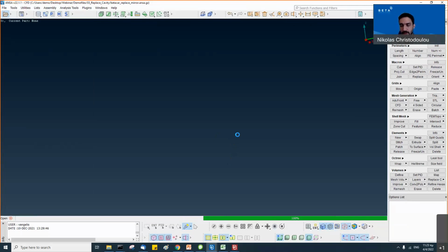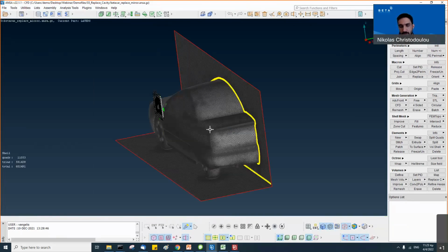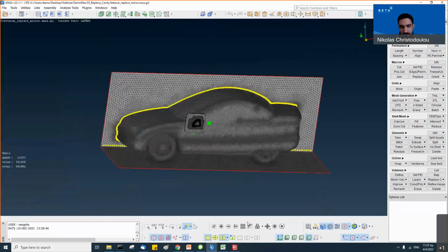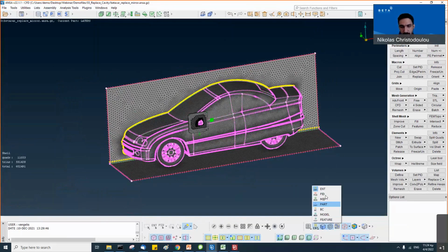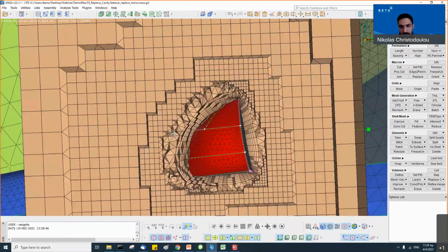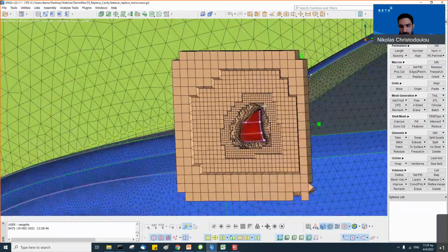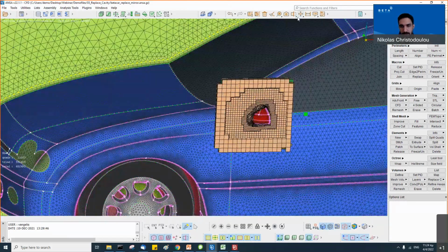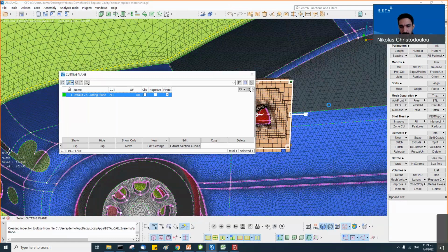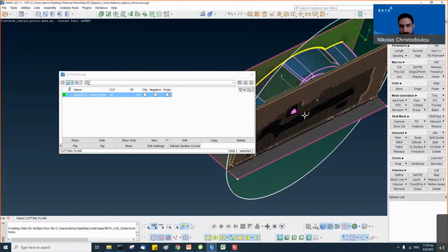This is a very handy tool because it's easy to do a model update on specific parts, and you don't care about anything else. You will just use the replace functionality, and ANSA will do the rest. So what we see here is a mirror that has layers and volume mesh. Now there's a cut plane, but it's finite, just to focus on this area. Let me show you that actually all the model is meshed and we can visualize it with a cut plane.